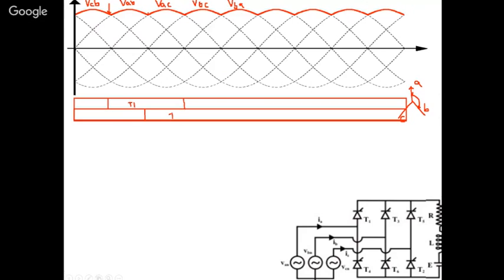So here, that is T2 is in the lower arm, so I have given it in the lower. And after this, after T1, it is the upper group, you can see it is T3. After T1, T3 will be on, and again after 60 degrees, your T5 will be on. I think you can understand this.